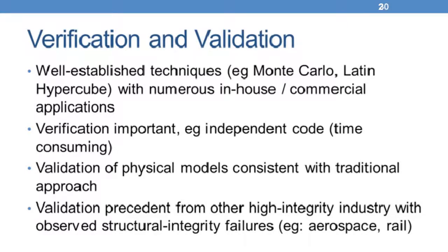And this can be achieved with an independent code, although if you're using Monte Carlo analysis, this will effectively double the analysis time. Spot checks of FORM analyses using Monte Carlo is also useful from a verification standpoint.